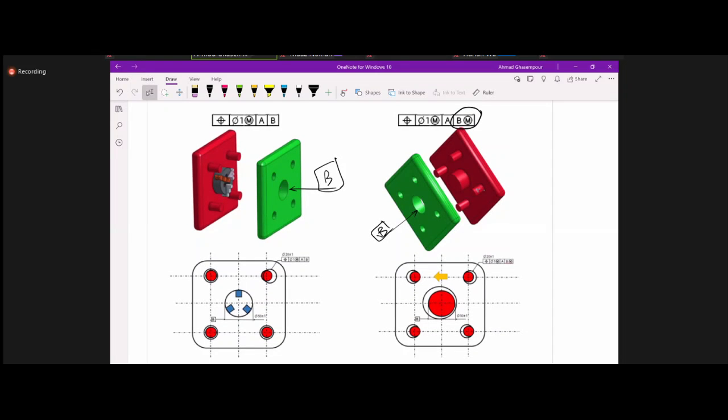Maybe it's easier to start with when we do have the M attached. When M is attached to the datum, that means the datum, which is this pin here, represents the datum of the part, is a specific size. And the size is the maximum material condition of that datum.